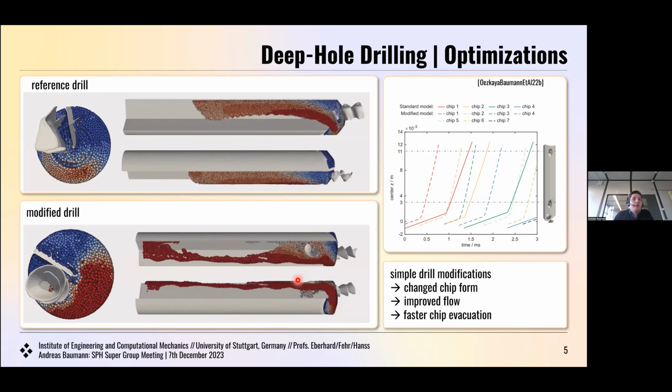I think in general, a good rule of thumb for the weakly compressible sound velocity is to apply 10 times the maximum velocity we see in the simulation. We did this in one of the first simulations. However, we thereby have a density increase of more than 1% in some places, which exceeds the assumption of our weakly compressible formulation. So we also need to adapt for a higher sound velocity, which of course comes with higher computational times.